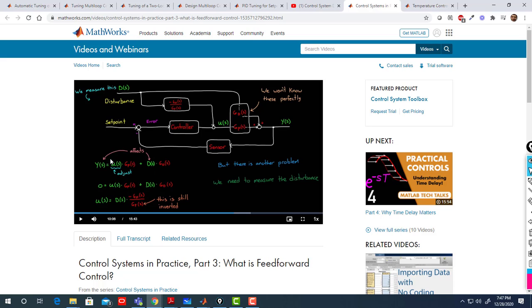If that's your transfer function, then what should my feed-forward controller be in the case of disturbance? Before, the aim was to cancel the dynamics of the set point and the steady state error, so it is the inverse of the plant. That's my feed-forward controller design.